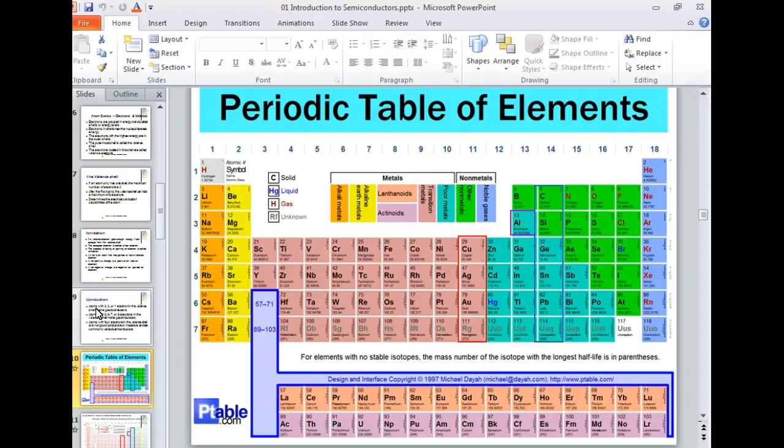But what is the advantage of using aluminum as a conductor? Yeah, cost. I mean, we're talking a big cost. So what we do is we compensate for its resistance in transmission lines by using an extreme high voltage, right?